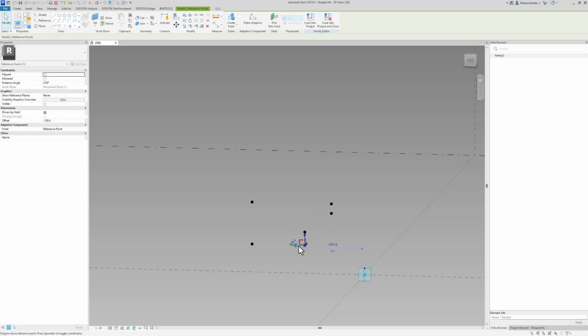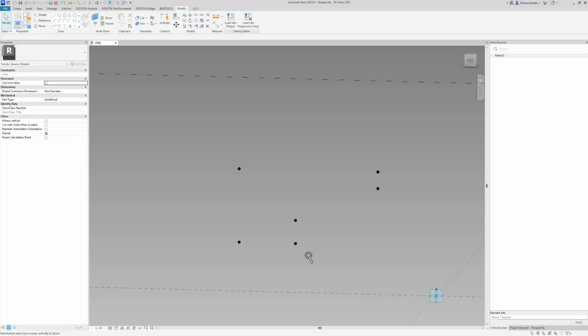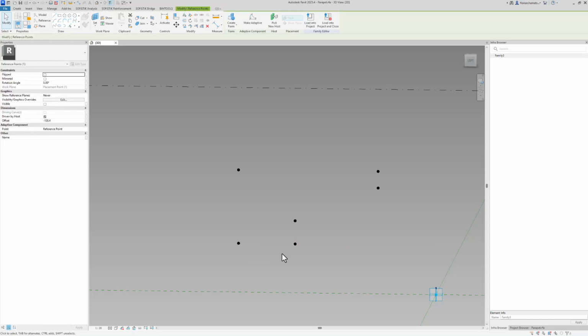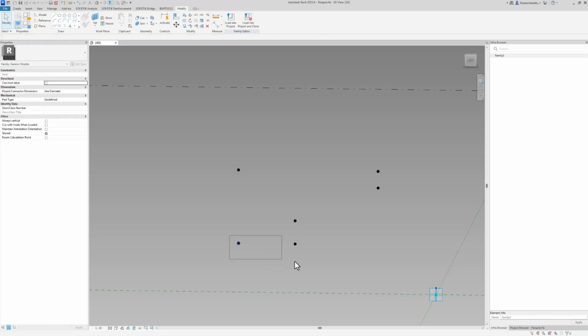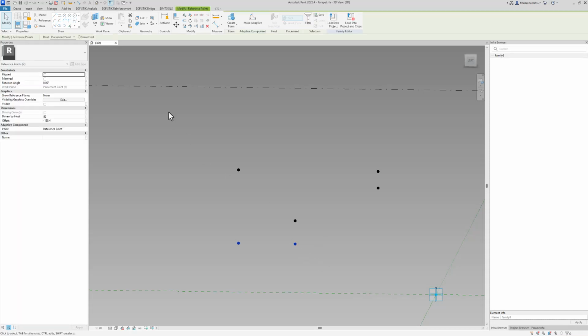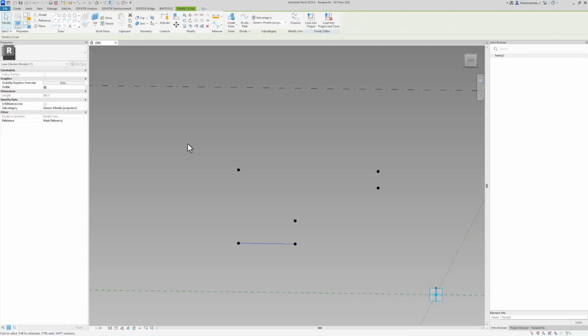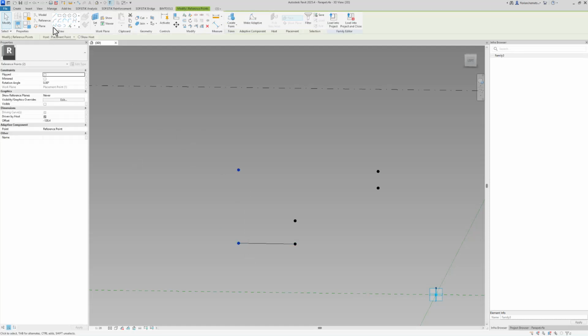I will now quickly just modify this a little bit for it to represent it. And what I want to do next is, based on these reference points, I want to create a new boundary. I select 2 points and click on Spline through points. This will automatically assign a line to these 2 points.